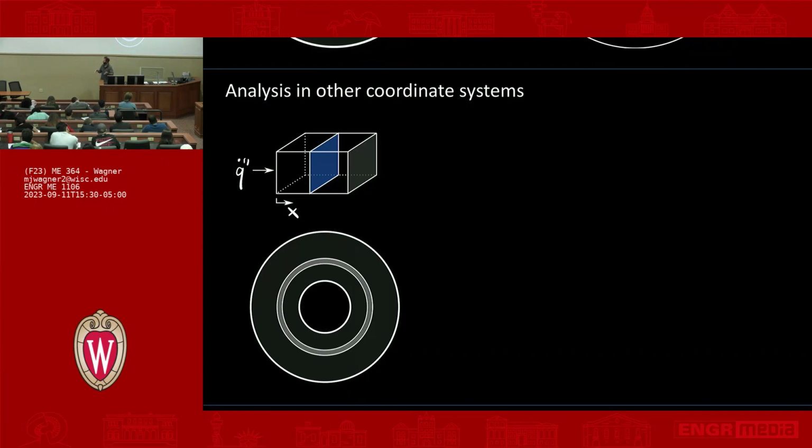We have to think about what's happening on the left-hand side and the right-hand side, because that fixes the problem to a certain solution. Here we have Cartesian coordinates with a left and a right boundary. Here we have our A_C, the cross-sectional area, which is not changing as a function of x for this particular example. Here on the very end, we have A_S. So draw that distinction in your mind: the cross-sectional area and the surface area could be different.